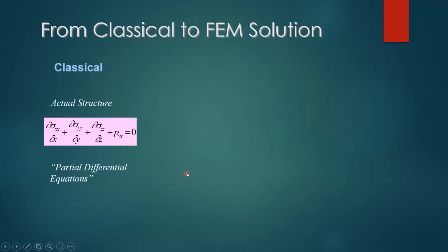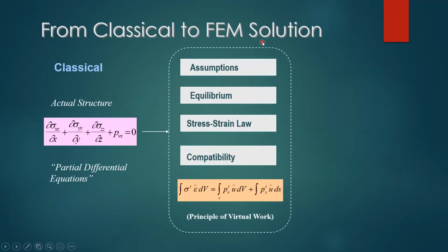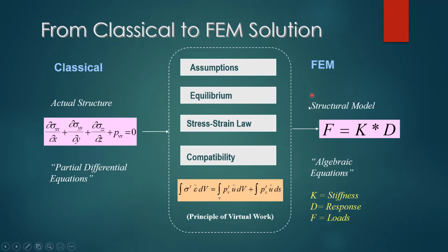Okay, so from the classical to finite element solution, you should see that from the partial differential equation, we go through the principle of virtual work to the structural finite element model. I'm explaining this because I don't want you to only use a model like a video game.